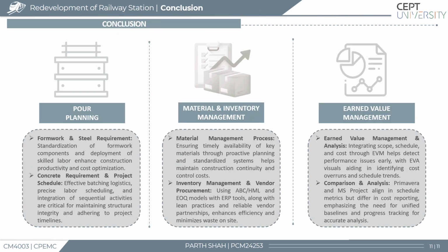Thus, concluding this integrated approach followed throughout the studio, project planning with detailed quantity estimations and productivity metrics highlighted the importance of sequencing and resource optimization. Material and inventory management applied analytical tools like HML, ABC, and EOQ to optimize storage, reduce cost, and ensure timely supply. Earned value analysis helped measure project performance accurately in terms of both schedule and budget, using MSP and Primavera for comparative insights. These comprehensive assignments collectively enhance technical proficiency and practical understanding of real-world project execution.